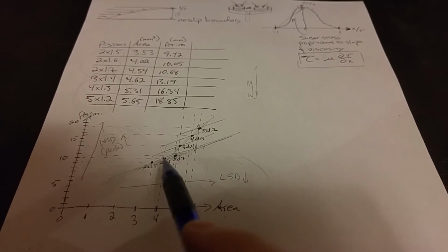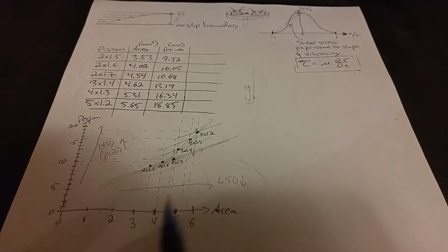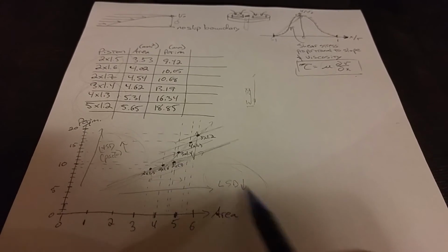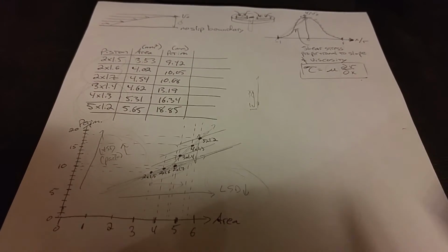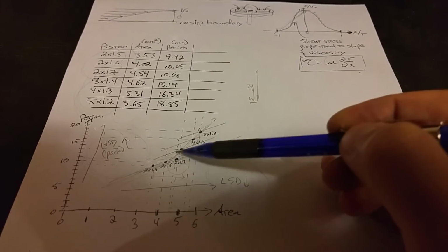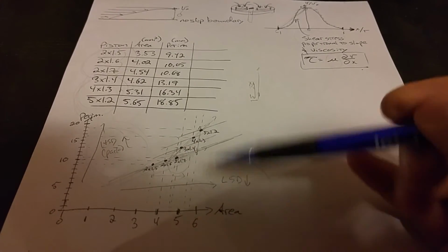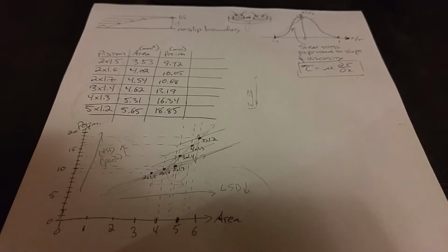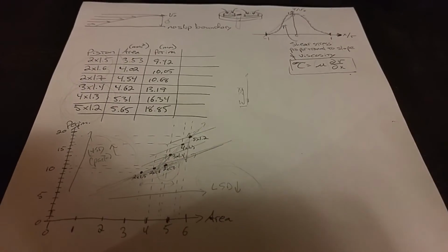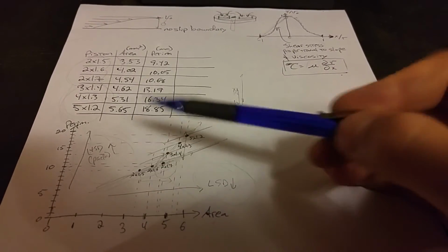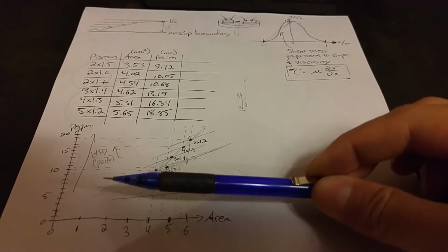So as I change the piston hole size, what I'm primarily modulating in the 2-hole piston range is my low-speed damping. So maybe I go to a 2-hole piston that has a larger piston hole size to give me a bit more of a plush suspension during cornering, but to also have less pack to handle high-speed bumps.